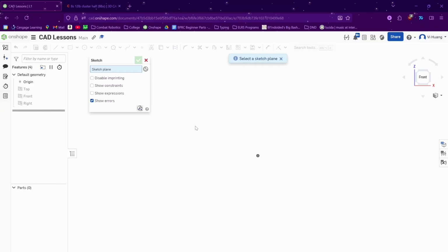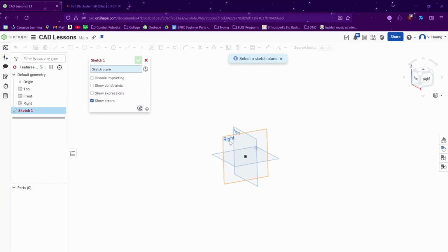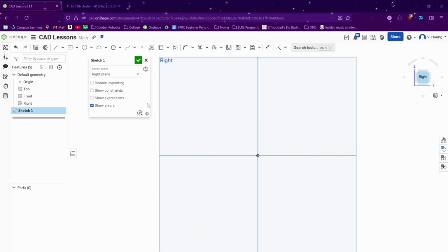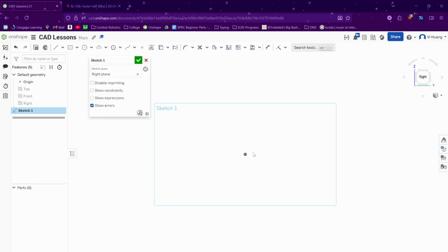So the first thing I do with any CAD is to define my sketch plane. When defining my sketch plane, the first thing I usually start with is a master sketch. This sketch is made completely using construction lines, and it is used to sort of set up all the variables, and it also contains all the references I use later on in my CAD.